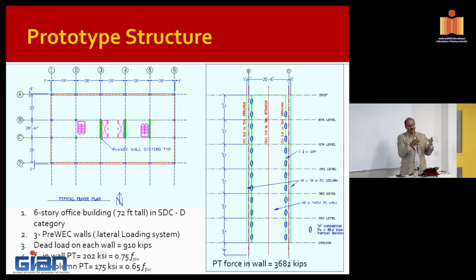So let's say you are building a column for a bridge. The seismicity requires a certain moment resistance. So you put in, I don't know what the bar size is, say 22 millimeter bars, a dozen of them. That was controlled by the moment demand.